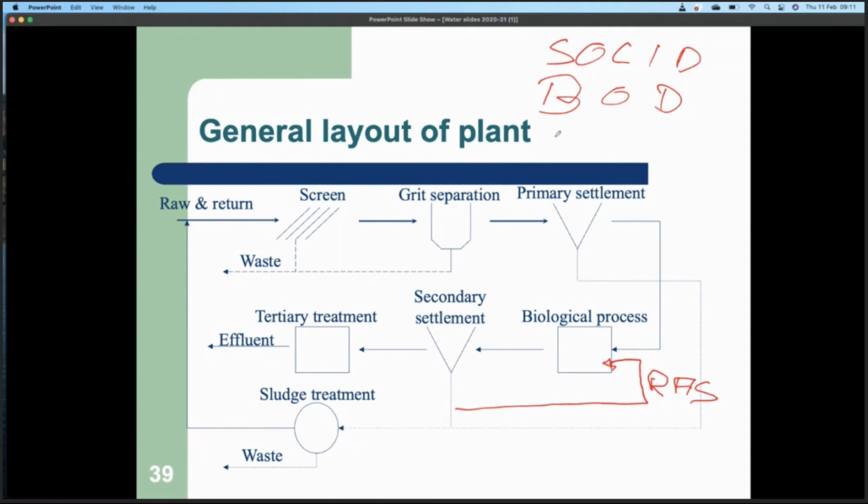And then the last thing really that you also have is nutrients. Nutrients are primarily nitrogen, possibly phosphorus, that get taken out. Some of the nutrients get taken out with the material that you settle out here, because there's some nitrogen in these substances. And some of the nutrients are removed in the biological process, and that is actually almost tertiary treatment.